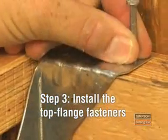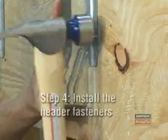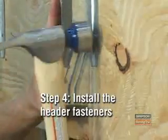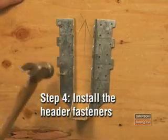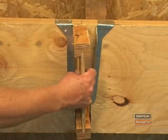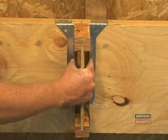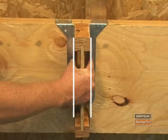Install fasteners to the top flanges and into the top of the header. Step 4 for installing either a face mount or a top flange hanger is to install the header fasteners through the header flanges and into the face of the header. The side plates of a correctly installed top flange or face mount hanger are parallel. In other words, there is the same distance between the side plates at the top and bottom of the hanger.